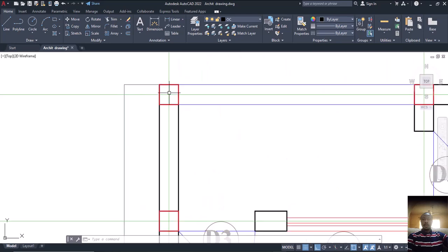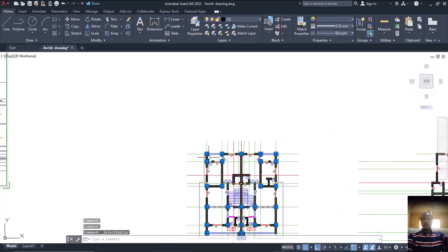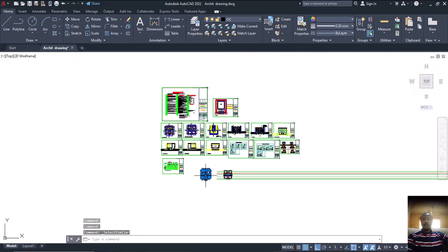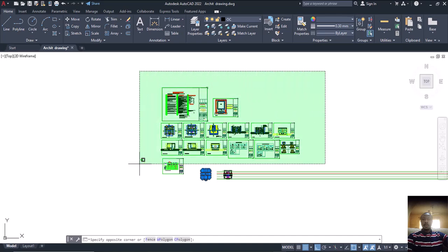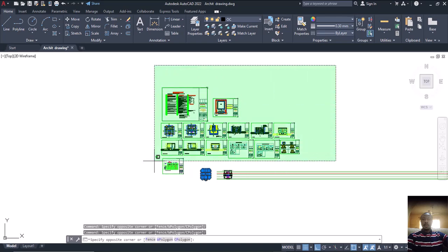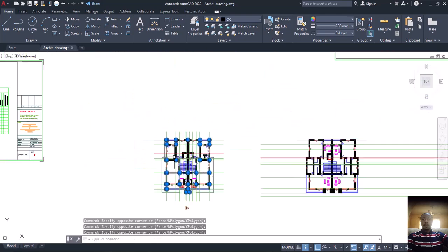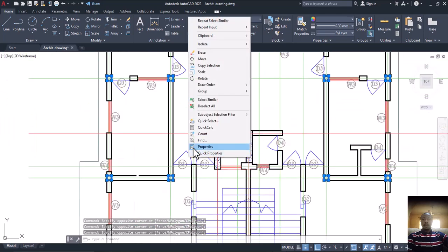So now let's click on this one. Right click and select similar. As I said, anytime you click on select similar, always check other drawings. Is that okay? So whether any of them is selected or not, I always like to deselect by pressing my shift key down and then moving my cursor over them. Is that okay? Do it again, because I don't want to hear a story that touches the heart. Is that okay? So I'll now come here now, then right click.